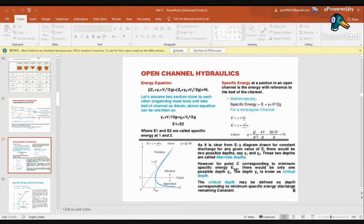Now your discharge per unit width is termed as small q. Okay, so here when E equals y plus v square by 2g, v can be written as capital Q by A, and capital Q is A into v.